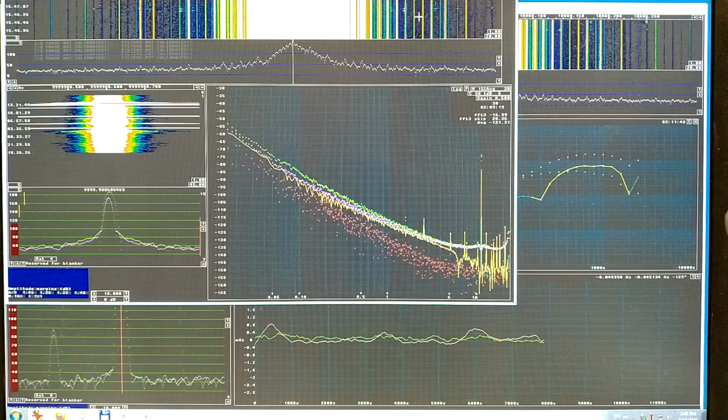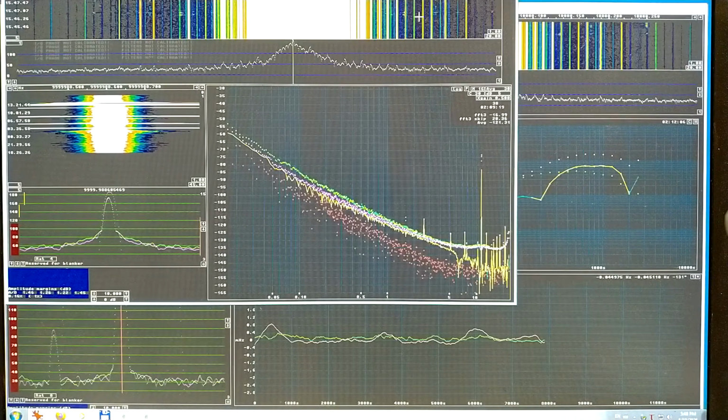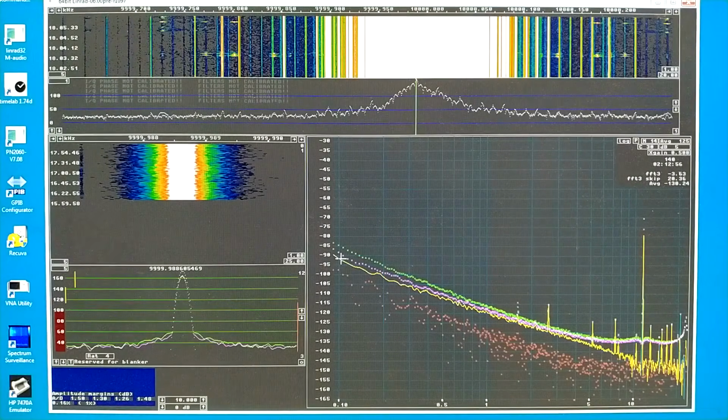Anyway, this is what I have arrived at, and I will let it be like this, because now I have a new project looking at polystyrene capacitors. I received a parcel today with ones that are welded rather than just squeezed aluminium onto tinned copper wire. I have set somewhat less demanding parameters. It starts now at 0.1 Hertz, and this has been running for 2 hours and 12 minutes.